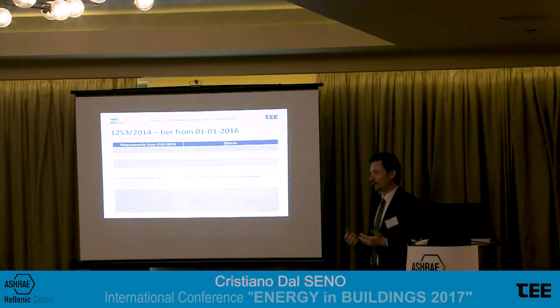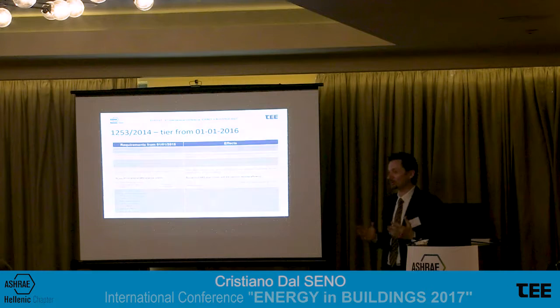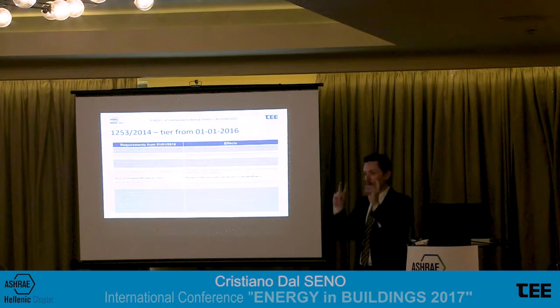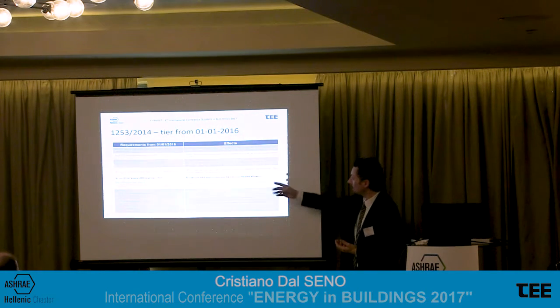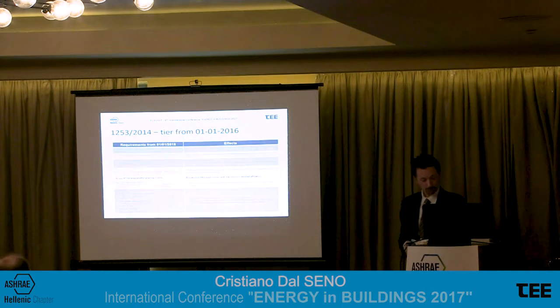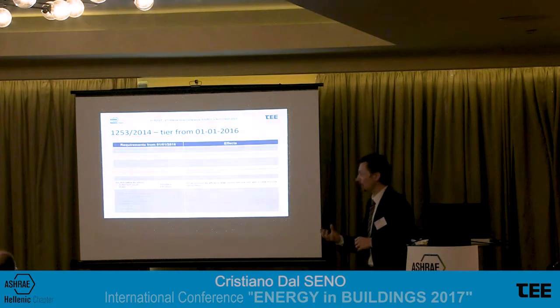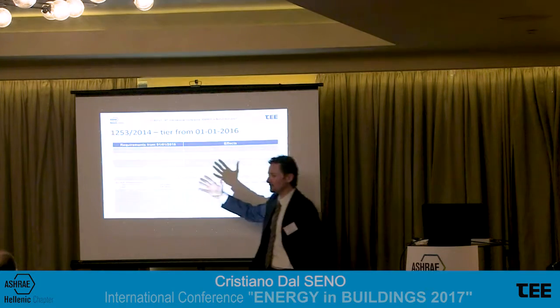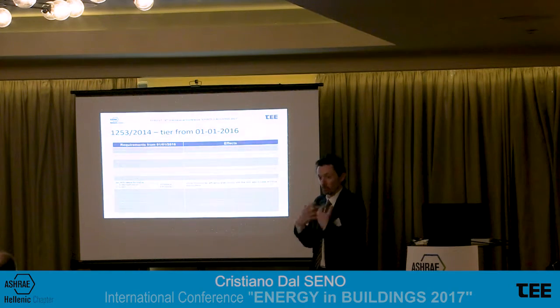5, 8 years ago, I used to select a plated exchanger with standard efficiency 50%, 40%, something like that. This was the common idea consultants and producers had to develop these recovery systems. Increasing the efficiency to 67% gave a boost to the size of these recovery systems and their capacity to recover energy. If we consider the efficiency in the heat recovery system, it increases the efficiency of the air handling unit because simply it helps us to recover more energy.